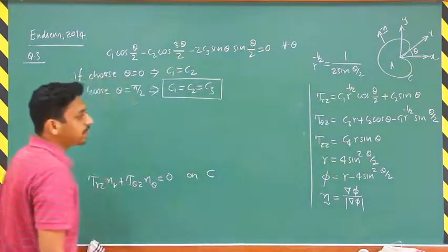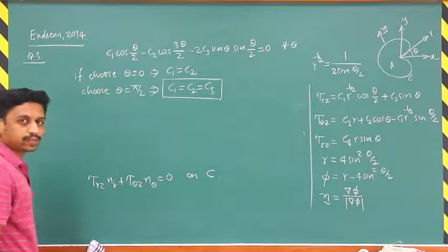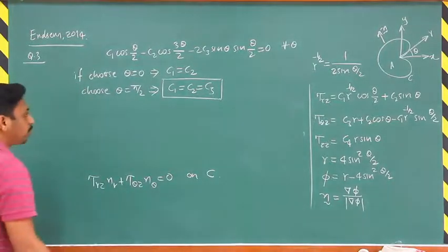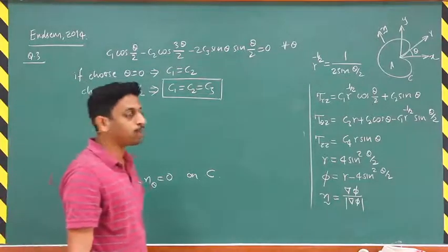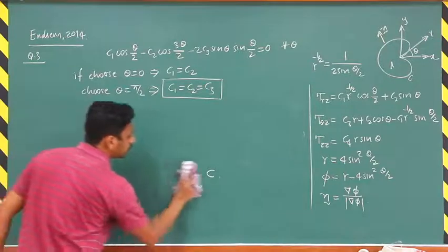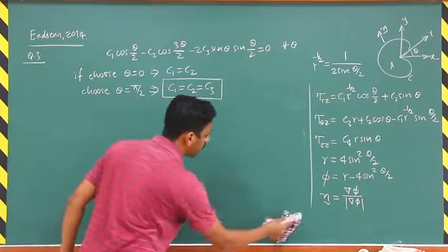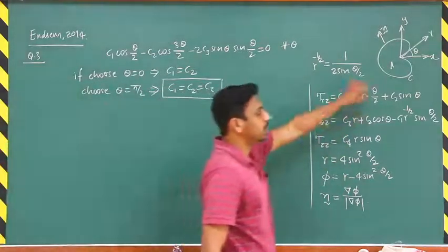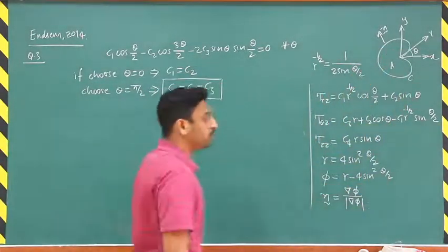To find these remaining constants C1 and C4, we need two additional boundary conditions which will come through the torque T and moment M being applied about the z-axis. So let's make use of these boundary conditions to find the remaining constants. We know that on this top surface, the torque T is being applied about the z-axis.